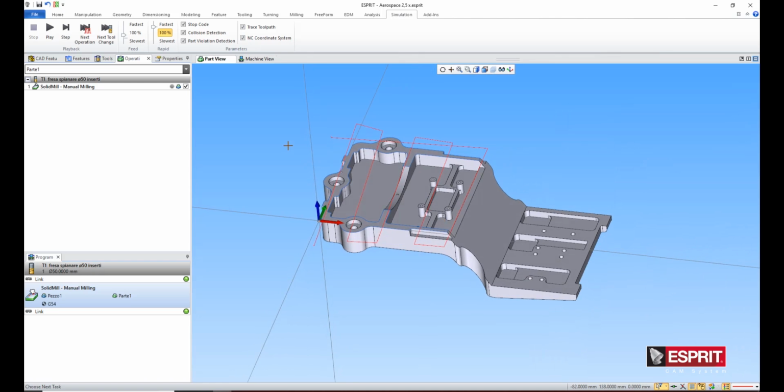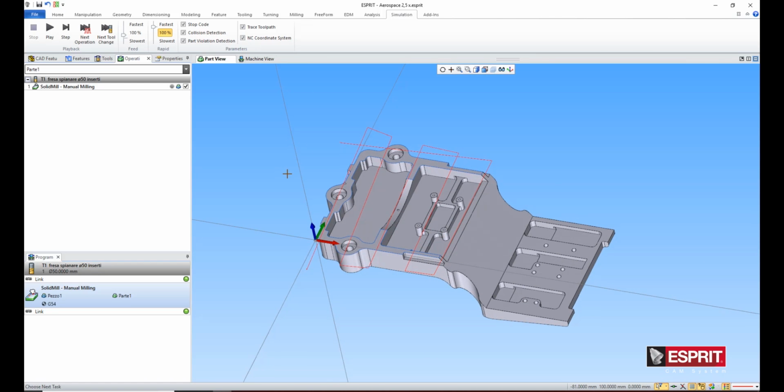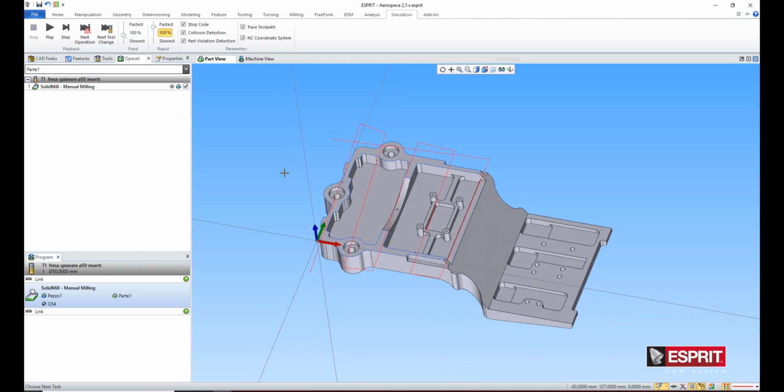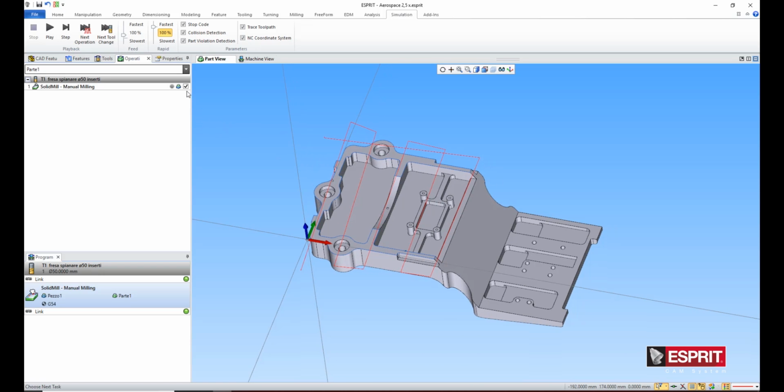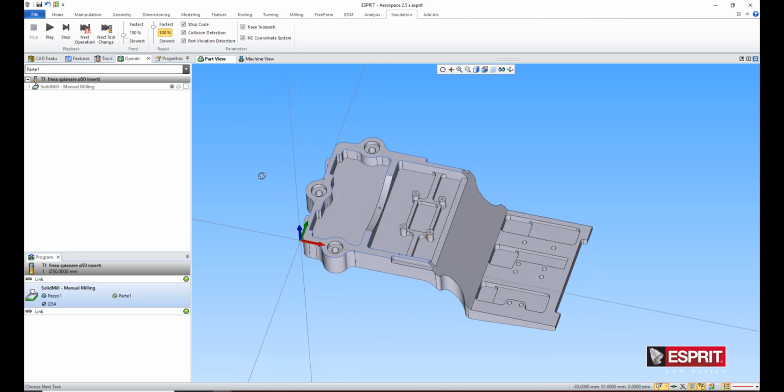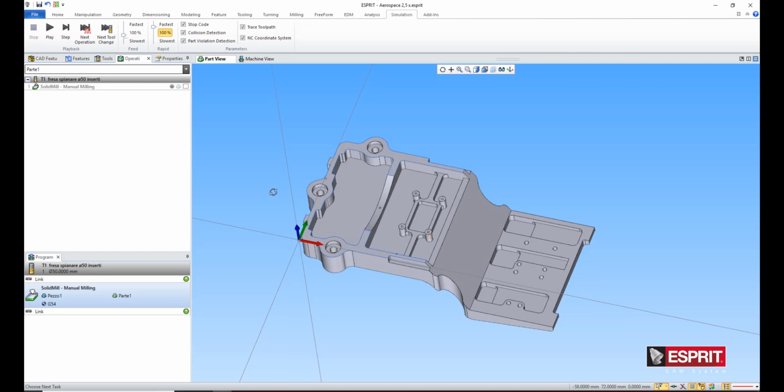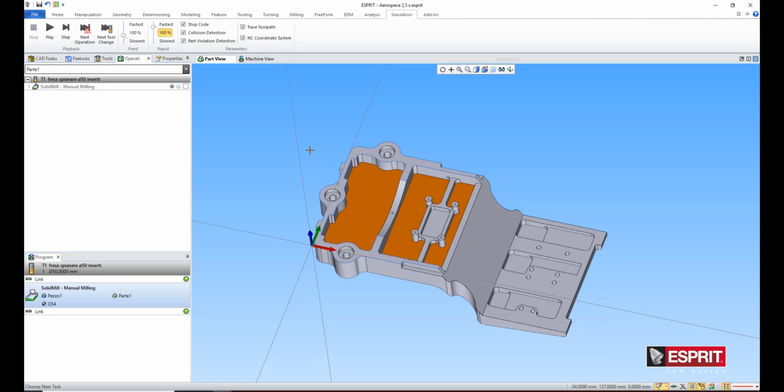The same strategy can be used to machine with different cycles. You only need to touch the surface to be machined. Suppose we have to do a pocketing in some areas. You have to touch in the bottom of the surface and then select the pocketing operation. A new window will follow with all editable parameters. Just click on OK to confirm the operation.